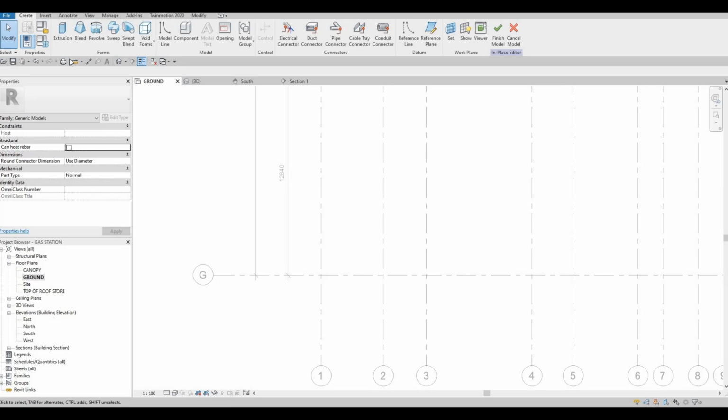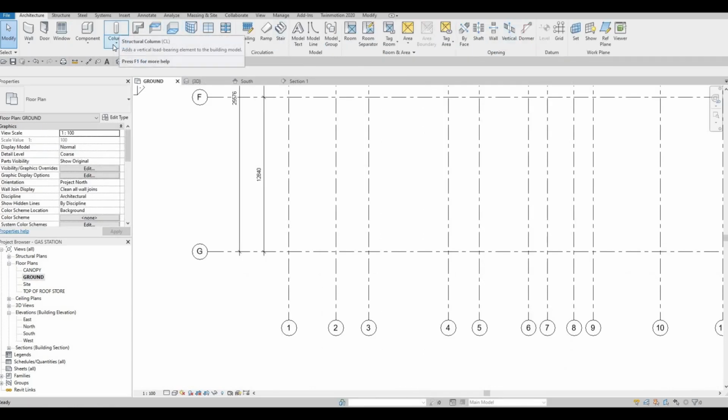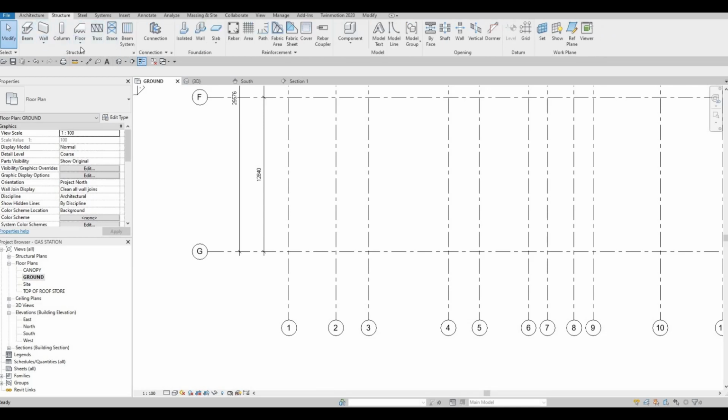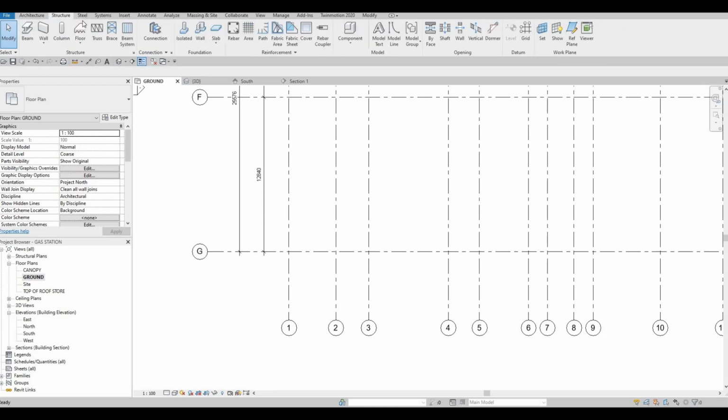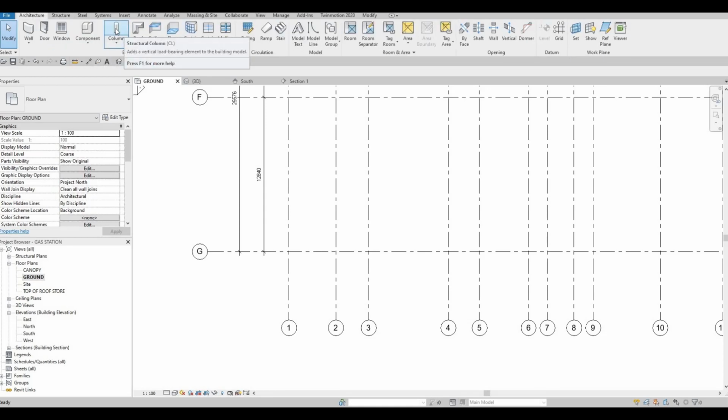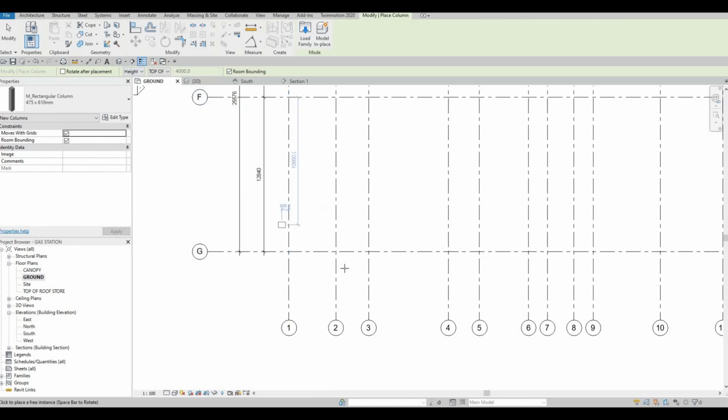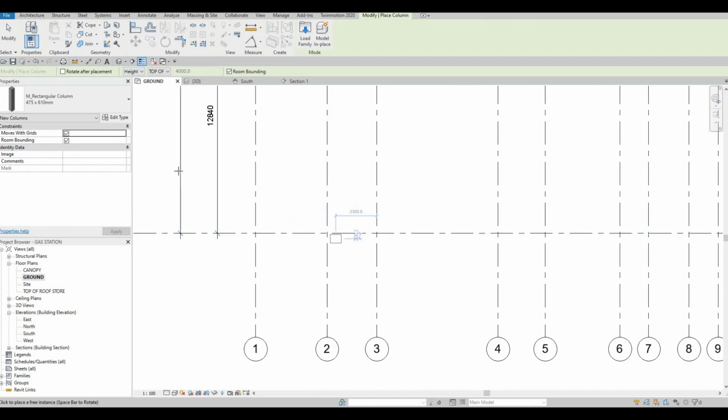So in terms of post, you can basically do whatever you want. Right now, I'm just going to use extrusion. You can even go and add different ones, like, for example, architecture columns if you want to. So you can go to structure, and then we have architecture columns right there. This is structural, and then this we have architectural columns like there. Here we could just add in columns that we think can be the same as what we're trying to do.